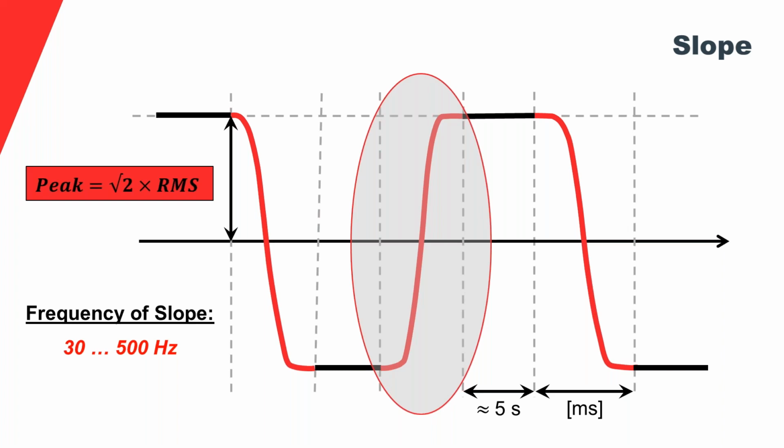The difference here is not the waveform, the difference is the parameters. And let me just make one thing clear, also a call back again to the other webinar. When you do a VLF withstand test, both waveforms, 0.1 Hertz sinusoidal and 0.1 Hertz cosine rectangular, are equivalent and get equivalent results if you apply the IEC testing conditions, which means everything is scaled in RMS values, which means that the peak of the sinusoidal is 41% higher than the cosine rectangular, because then the RMS value is the same.